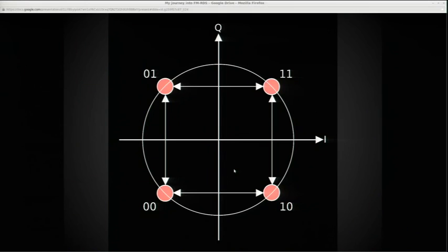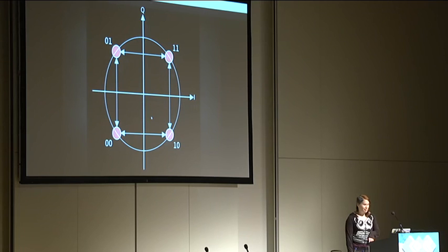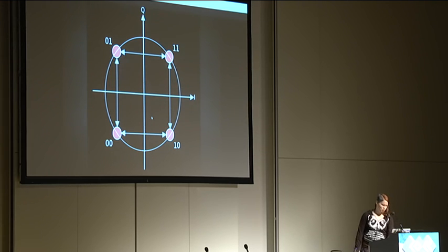Well, I'm not an engineer, not a DSP specialist. I'm a DSP hacker, but I don't know much about demodulating QPSK. So I decided to treat it as an FSK signal, because that is possible with QPSK. It's, how should I say, suboptimal, but it works. I can get the data out.